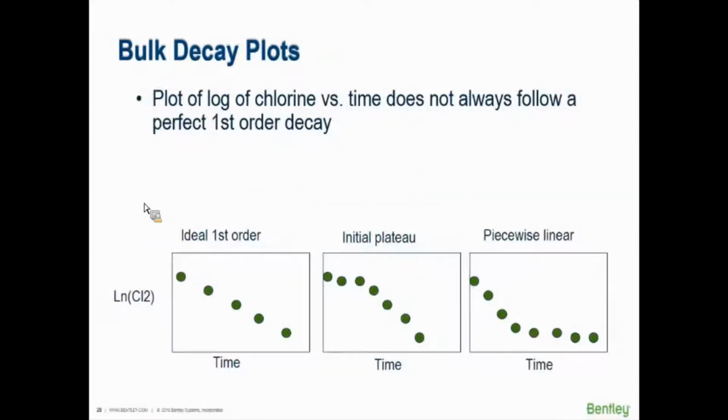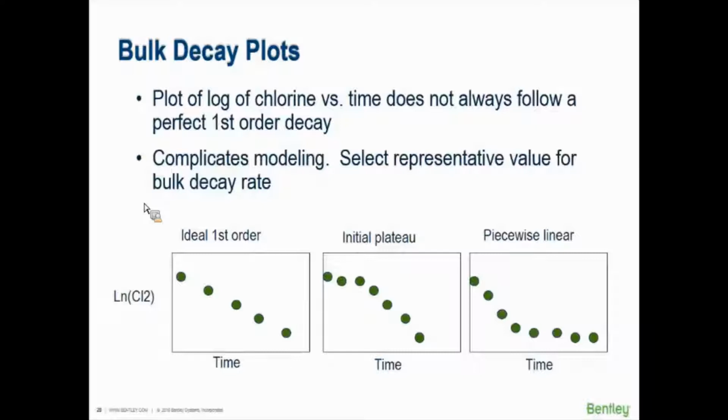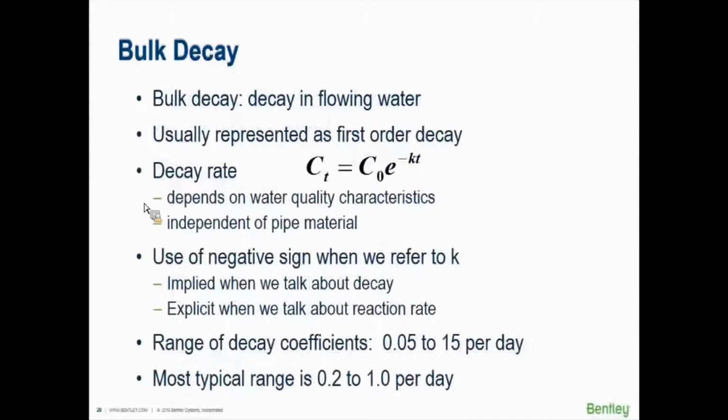What the reaction rates really are, they're a log of, in this case, chlorine decay over time, reaching zero at some point. What you're going to end up needing to do is to come up with your own reaction rate for your system. There's book values that you can start with, certainly, but this is a little bit complicated to get to sometimes if there's a lot of other mixing in your system. How you get to the bulk reaction rate itself? Well, first, you're actually going to have to test that somewhere, and I believe I've got a slide in just a little bit that'll show you how to do that.